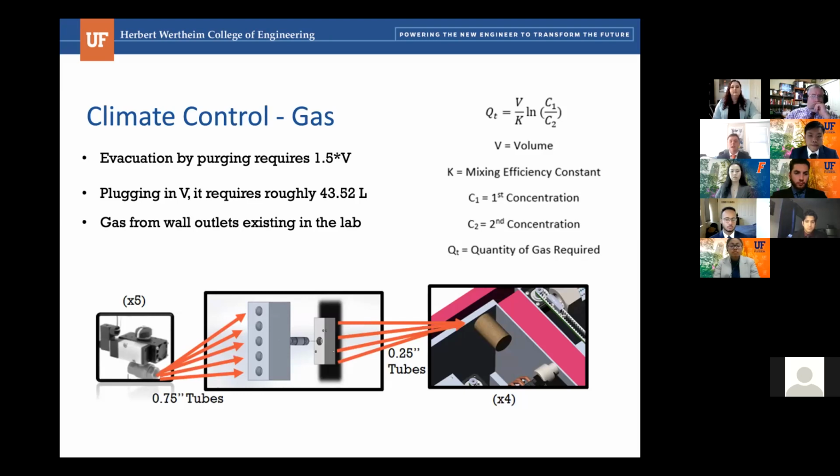From the valves, each gas is routed through a gas mixing chamber. From the gas mixing chamber, a pipe nipple carries the gas into a 1-to-4 gas manifold. Each outlet of the manifold will have a 1/4-inch diameter air hose attached to it. These air hoses will carry the gas from the gas manifold into each climate-controlled area. The gas will enter the area using a pipe coupling with the other end of the pipe coupling attached to a fine pore diffuser. The coupling will also be sealed around the outside with caulk to assure that each climate-controlled area is airtight. Gas is released from the climate-controlled system using a pressure-activated valve.